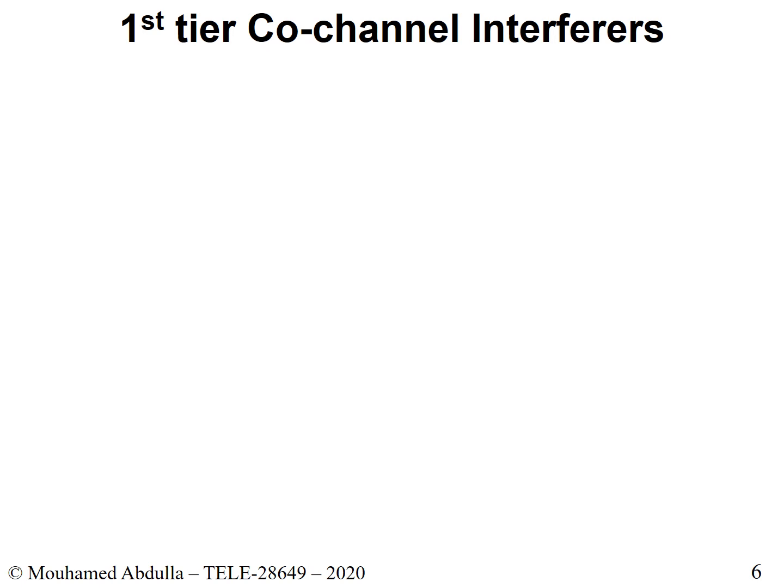However, when we look at the interference, it is not a bad idea to always begin with the first tier. You can certainly go with second tier and third tier, but that becomes a bit too cumbersome. And also, not only is it too cumbersome, you might be doing too much work with not so much of benefit, right? So the impact could be negligible. Although one has to also be reminded that interference is always measured at the aggregate. So I don't want to totally discard second tier and third tier interferers, but let's just focus on first tier for the moment. It will make the analysis much easier. And also, it is somewhat plausible to believe that second tier and third tier will contribute to the interference, but it will be to some extent negligible.